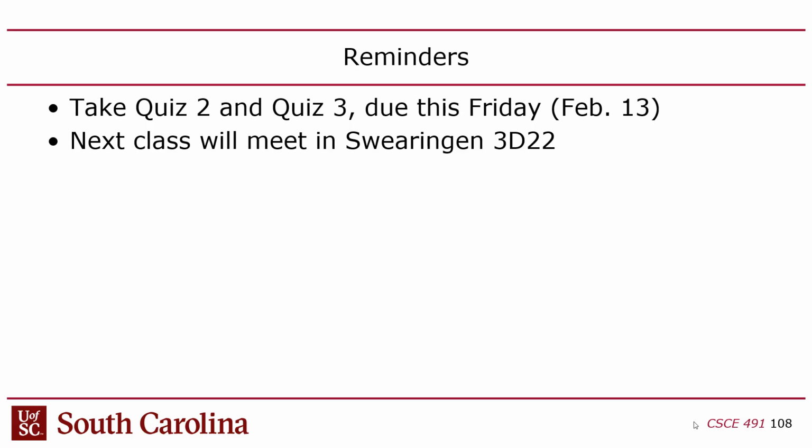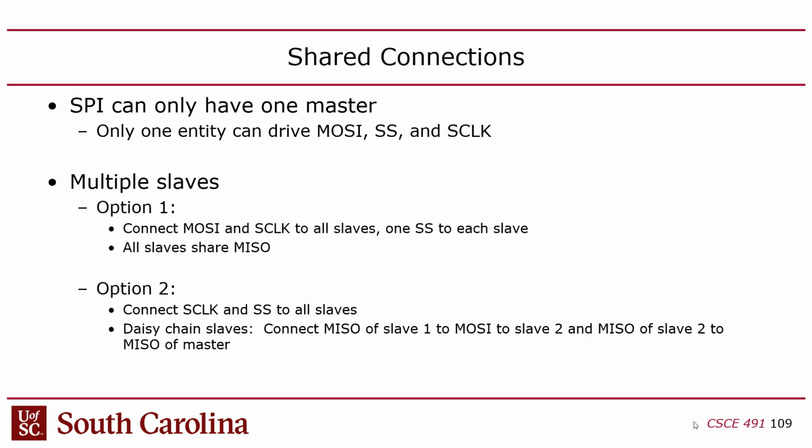So last time I talked about UART. Are there any questions about UART? Okay, and I think I started talking about I2C last time. The way I introduced that is that SPI has this limitation where, generally speaking, you have one master and one slave on SPI. SPI is essentially a point-to-point connection. There are ways to have multiple slaves, though.